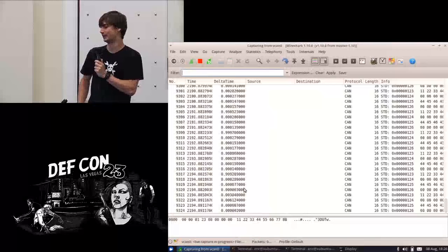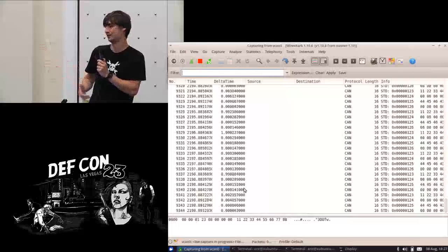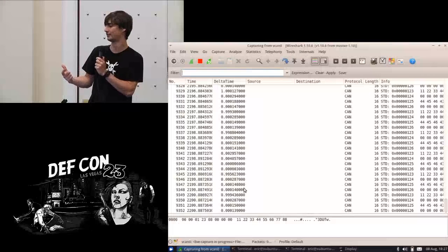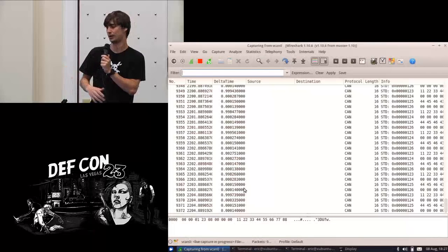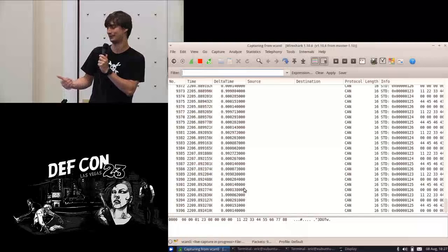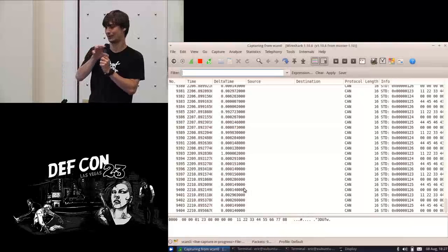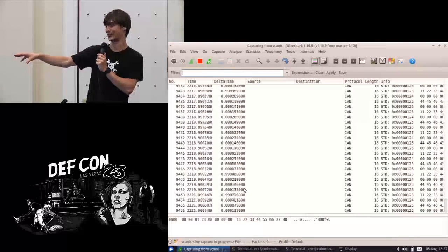In simulating, if you're doing VCAN simulations, the easiest way to do it is you treat the VCAN interface like a CAN bus, and you just make everybody connect to it. So you can also use it for piping messages around. I've seen at least one script that took messages from a real CAN interface, moved them to VCAN, doing some filtering and some reassignment of IDs, and then moved them back to a different CAN interface.